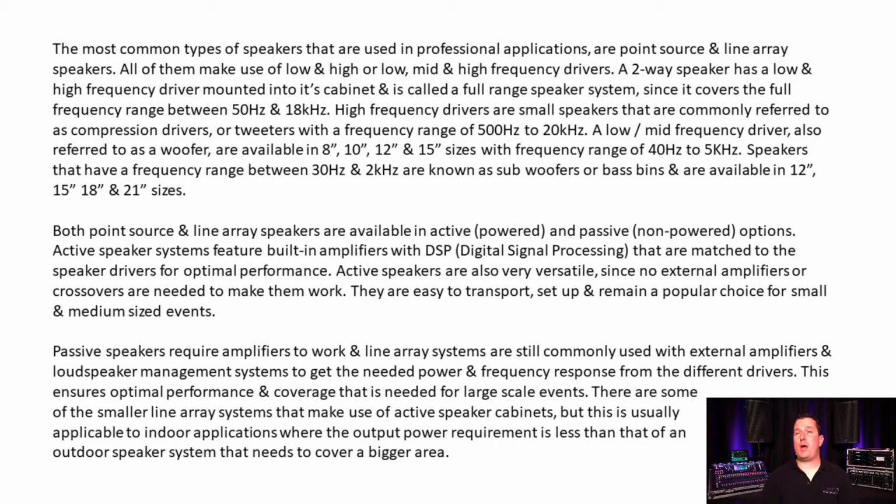Passive speakers require amplifiers to work, and line array systems are still commonly used with external amplifiers and loudspeaker management systems to get the needed power and frequency response from the different drivers. This ensures optimal performance and coverage that is needed for large-scale events. There are some of the smaller line array systems that make use of active speaker cabinets, but this is usually applicable to indoor applications where the output power requirement is less than that of an outdoor speaker system that needs to cover a bigger area.